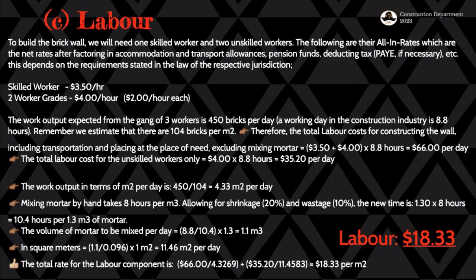So the gang had 4 workers, but here we're going to have 3 workers in the gang, who are expected to lay at least 450 bricks per day. And a day in the construction industry, according to our standards, is around 8.8 hours. So we have to consider that, and then we have to remember that we have 104 bricks per square meter. Don't forget that.